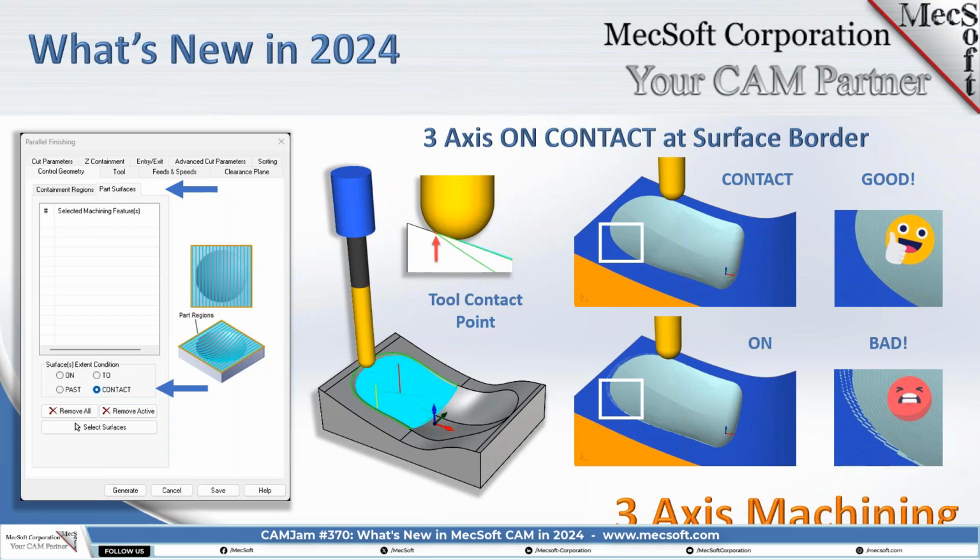That's very important for maintaining an accurate and clean parting line. Previously, you had to do some additional modeling to get some surface to help that tool go past that parting line and cut a clean and exact parting line. Now you don't have to do that, and this works very well on a number of types of cavities, and we'll show you an example there.